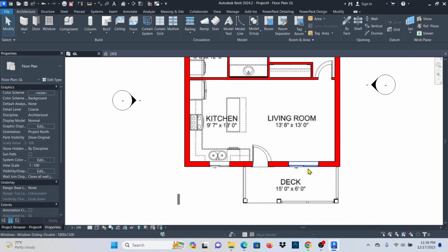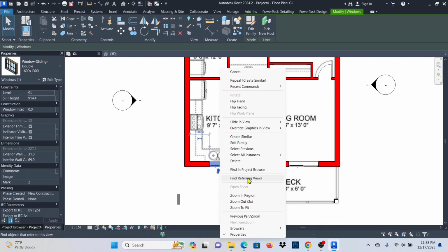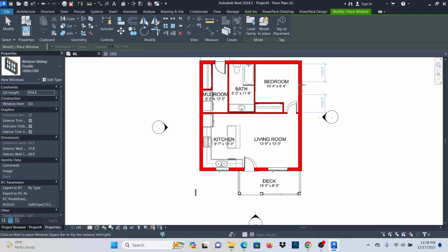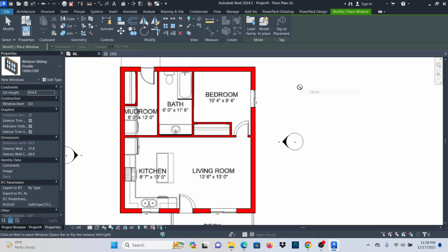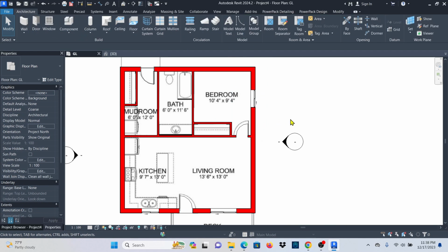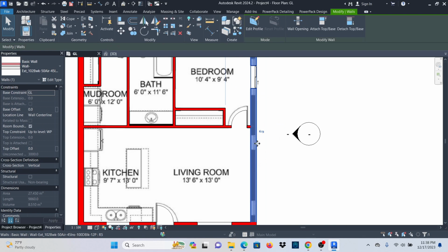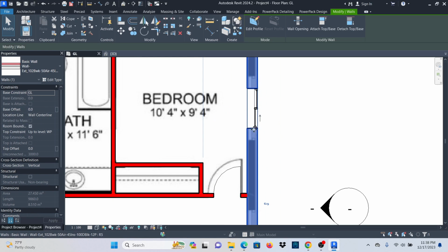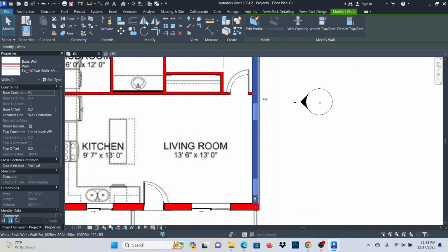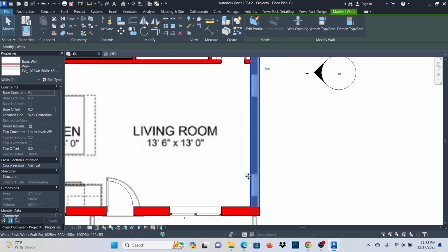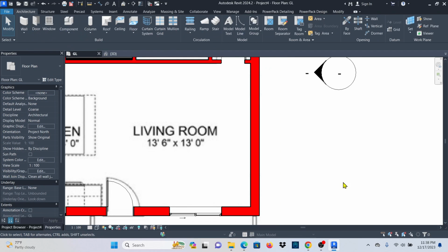So this is for the living room. It's much bigger. I can select this one, create similar, and maybe it should be the same here. Now if I want to see what is in the background, I can just select the wall there. See that this one is smaller, but I know I want a bigger one, but it's okay. I can rename it. I can go to the library and find the correct ones, the bigger ones, and resize it from there.